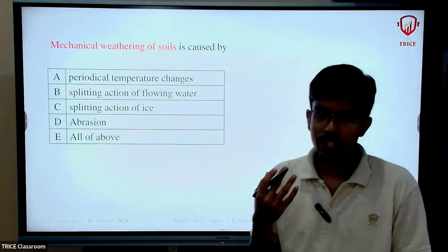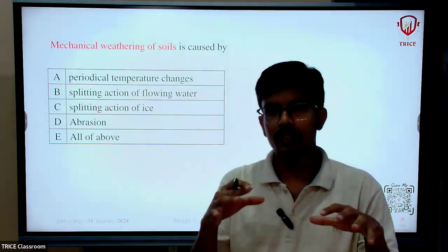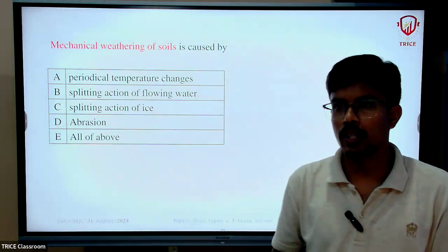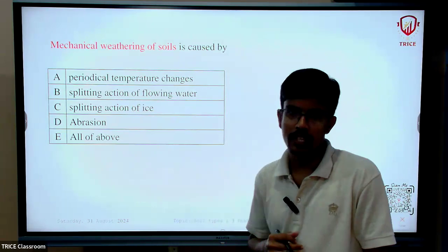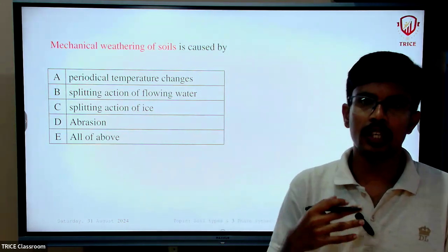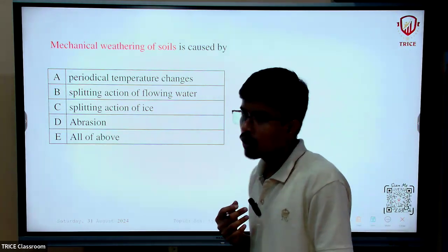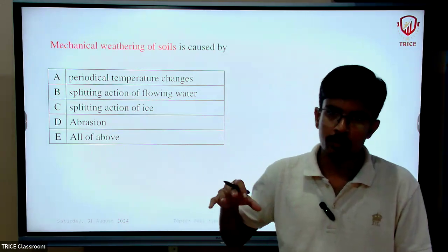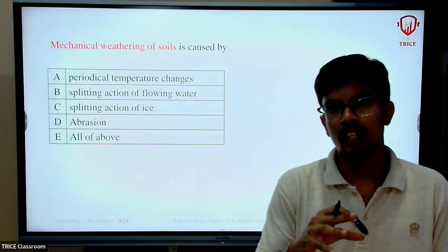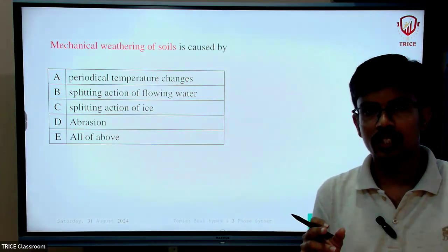Due to heavy temperature, when the temperature is applied to the rock, the rock disintegrates. There are periodic temperature variations, alternate freezing and thawing, and temperature rising. Then there is the action of the flow of water. During the movement of water through the soil, it creates spaces in between the soil particles, washing away the fines.